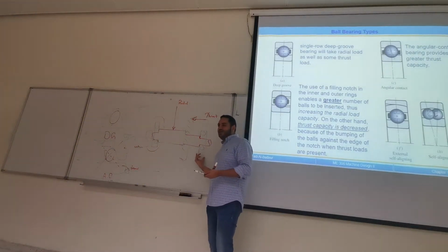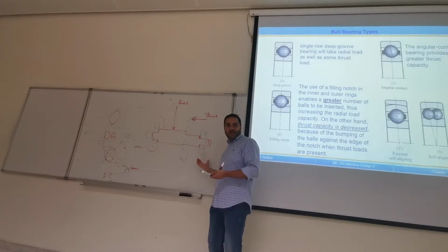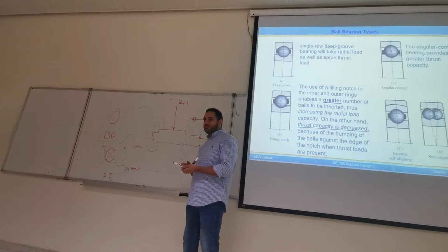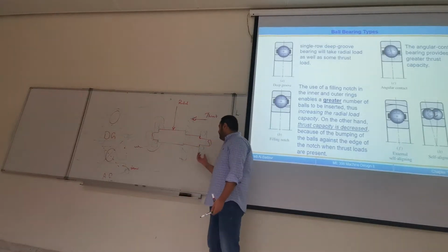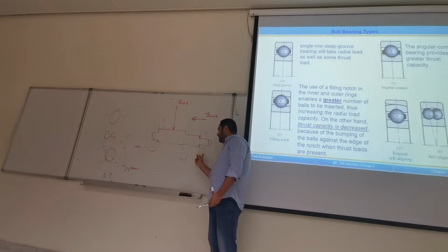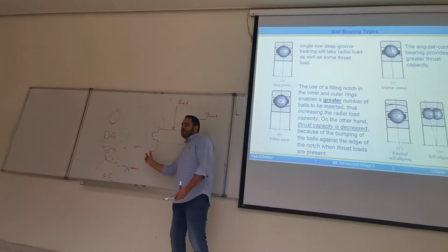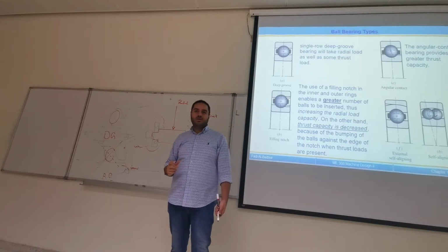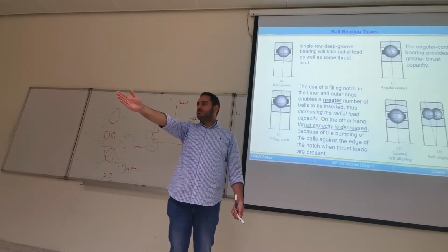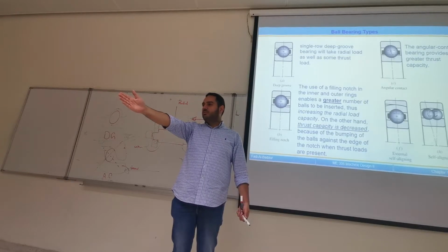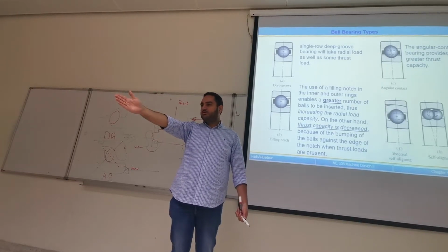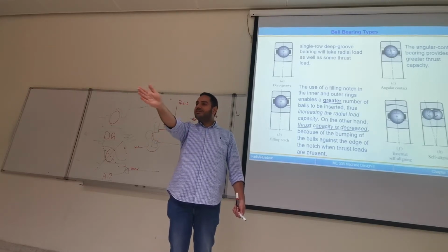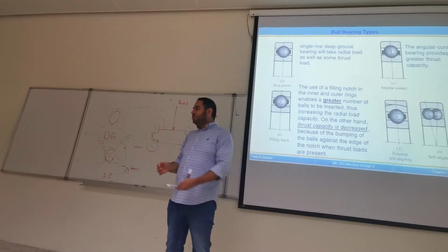Now this bearing is not in the air, it's fixed to a structure, the bearing housings. And this one also is fixed to the bearing housing. Now, if the bearing housing here is not aligned with the bearing housing on the other side, what will happen? The shaft will remain straight or tilted? It will tilt. This is not possible. The shaft cannot tilt. It must be straight, either vertical or horizontal. I cannot make it tilt because it cannot deform.